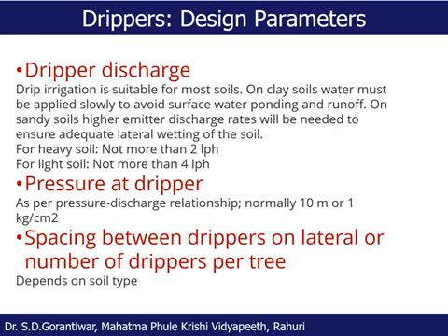Now, when some of the water builds up on the soil surface, because we adopt the drip irrigation method on rolling topography, there may be certain slopes within a smaller area as well. As head builds up because of the ponding, the water will move from the tree rows or crop rows into the drier area, and that area will be wetted unnecessarily.